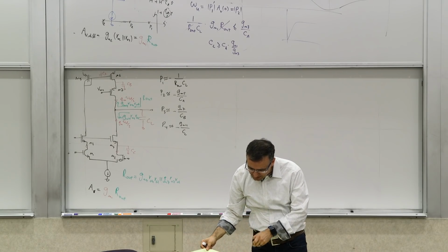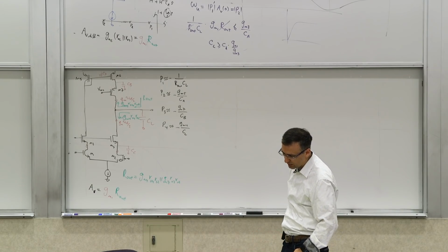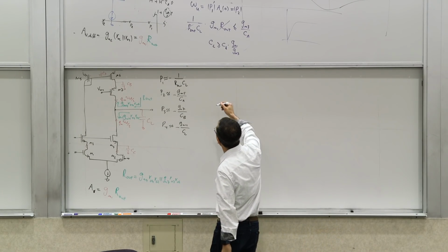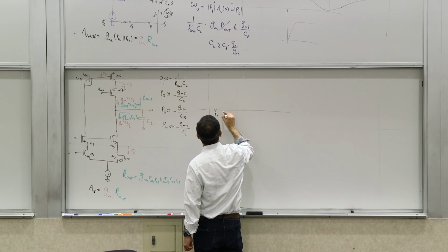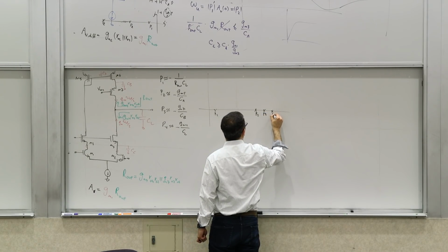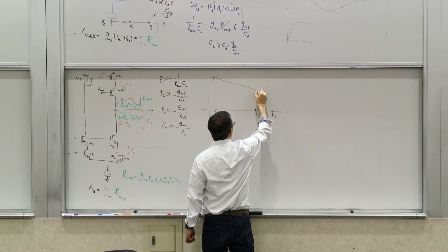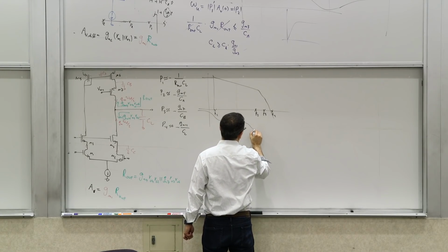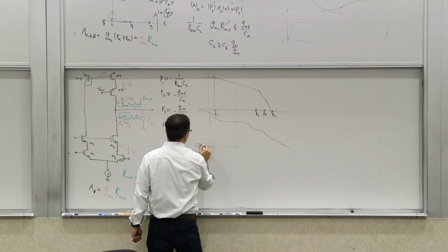And you're trying to compensate this. You're saying, okay, well, I want to make sure that this is stabilized. So what do we do? Well, you have 4 poles according to this simplified model. So you have one P1 here, and then you have a P2, P3, and P4 down here. So you go up here, you start dropping, and you drop more, and your phase goes down, and then asymptotically you can get negative 360 degrees.